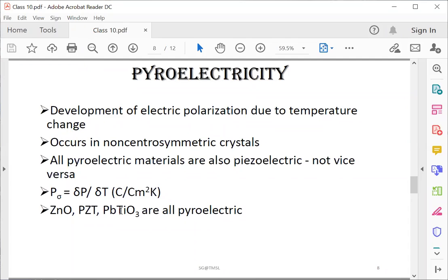But if you go for MEMS based methods for making those sensors, then obviously you have to choose a material which is friendly to the VLSI process, because you should not contaminate the whole process equipment or accessories by lead contamination. So out of the three materials, zinc oxide is much more popular, and a lot of work is going on based on zinc oxide nowadays.